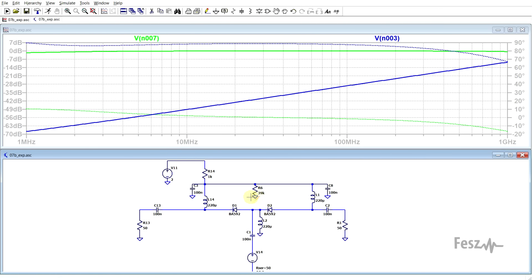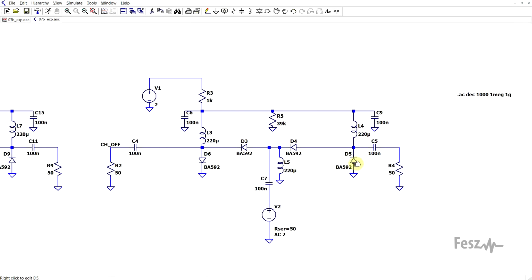Anyway, to enhance the effect, I added in a second set of diodes, so both of the switches are now combination series parallel switches. The diodes are placed so that one is always conducting and one is always blocking, and the idea behind this should be that this arrangement should have a minimal effect on conduction, but it should help with the blocking.